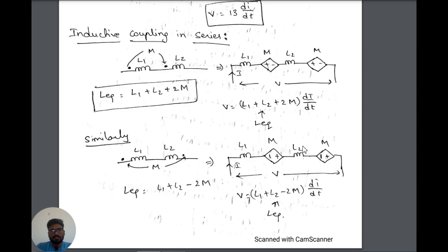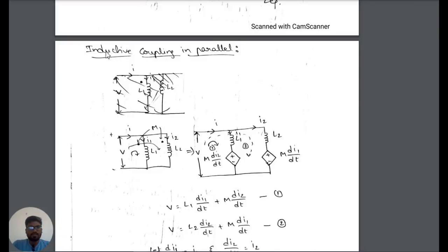So how I drew this equivalent circuit is, L1 is as it is, mutual inductance as it is, this mutual inductance is due to the current in this inductor. So as it is leaving the dot, the beginning point will be negatively assigned. So L2 is the same. For the mutual inductance that is caused by L1, the current is entering here. The dotted terminal will be positive.